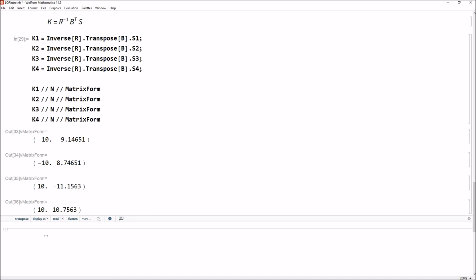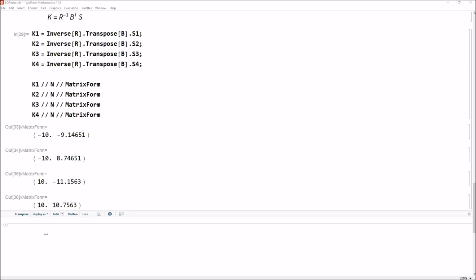They have different signs. They have different numeric values here. So theoretically, or at least mathematically, all of these solve the problem. But we know from an engineering standpoint here that they can't all work. Only the ones that have stable closed-loop eigenvalues actually will give us a system which goes back to the origin and therefore has minimum cost in our cost function.